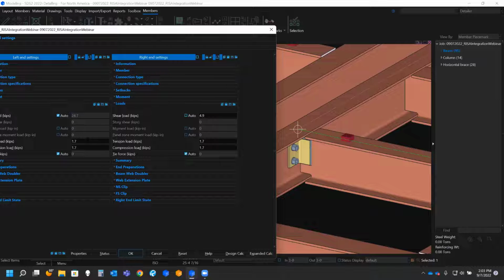That's a pretty strong connection. So in this case, you don't necessarily notice it, but when you start getting into some bigger, heavier connections, bigger bracing connections, things like that, that blanket percentage can really increase the size of the connections, and you start requiring doublers and stiffeners all over the place. And when we start doing those types of things, it really increases the cost of our connections.